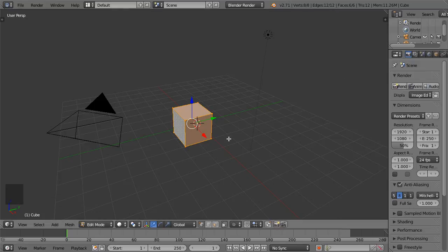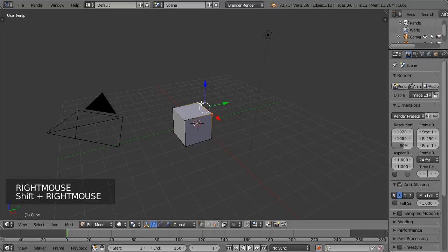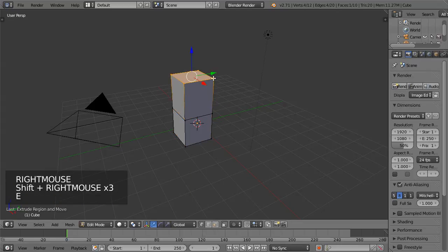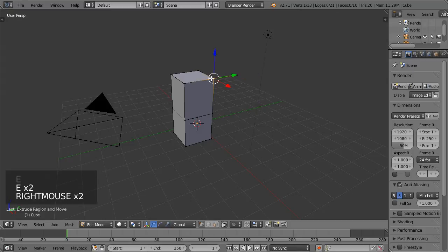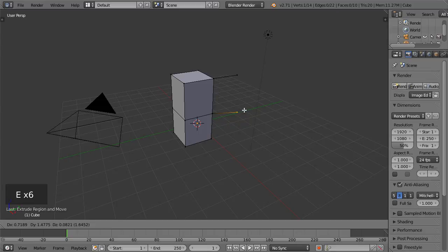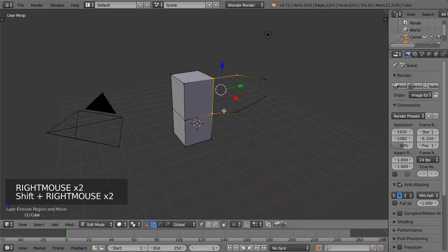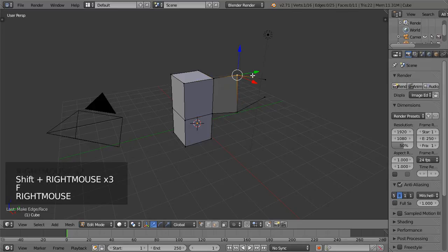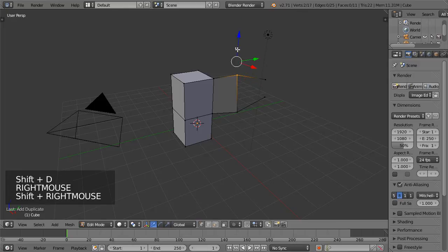So we've already added our mesh. Now we can extrude faces. We can extrude single points off of our mesh, which is not something most other programs allow you to do, at least not by default. All right, so now we can turn these points into a face by hitting F. And if we remove the point from that, we can select both of these and hit F to make an edge as well. So F is to create edges or faces.